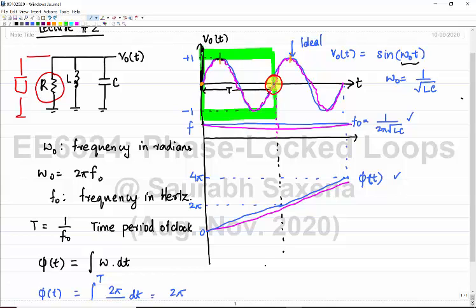yeah, so I am doing all kinds of zigzag, I start from this point, I do all kinds of zigzags here and there, maybe much more, but when I cross 0, I cross at the right point, and then I again do a lot of zigzag, and then I cross another 0, that is also at the ideal zero crossing location. If I do that, and if I am only interested, it depends on the application, if I am only interested in zero crossing, it's fine with me, because my rising zero crossing going from negative to positive is fixed, and which marks an event in the system, and I am going to synchronize my data rate or other things, or even the sequential logic with the rising edge,